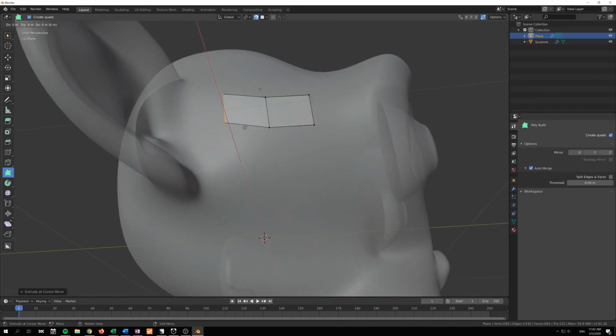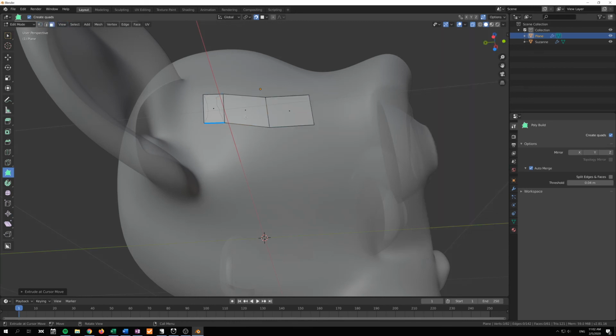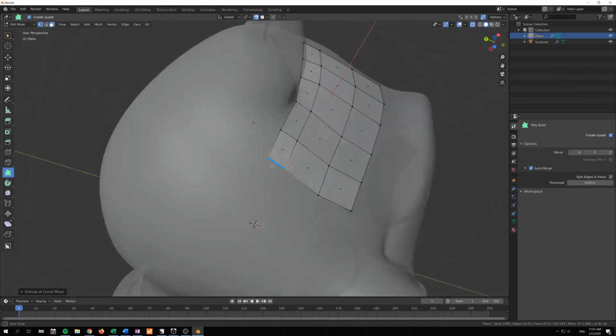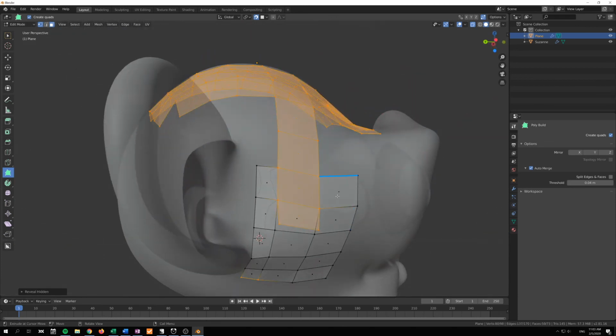can I create one here perhaps? That's interesting. Let's enable the center there, just enable that for a while. Alright, well, solve it by doing a kind of a loop around there. And then we can just continue from here. We don't have that problem with viewing the mesh on the other side. When we want to bring it back, just Alt and H, and you can bring that back there.